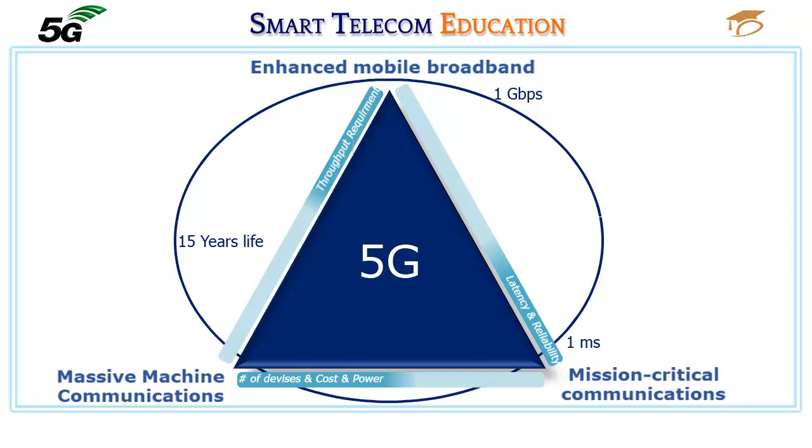Of all the above technologies, ultra-reliable low-latency communication will be the most stringent to achieve based on the 1 millisecond end-to-end latency, link reliability of 99.99999% and error rates that are lower than 1 packet loss in 100,000 packets as recommended by the ITU. New techniques are required to meet the stringent latency and reliability requirements for ultra-reliable low-latency communication as we migrate into the domain of haptic communications, tactile internet, intelligent transport system, and Industry 4.0 era revolution.